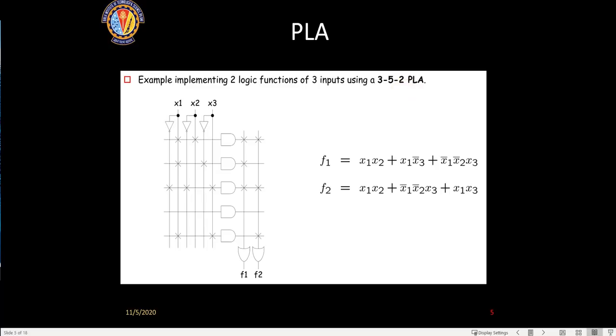There will be very user friendly software to program it. You don't have to really do all these things. There will be some matrix kind of thing which you will have to fill, like you filled the ROM matrix. We are not going to learn the programming language for each of these PLAs, because each PLA will have its own small code and software which will give simple instructions. You can just pull the PLAs, do the interconnections and write some functions there. Each company has its own small program, and it is fairly simple to program.